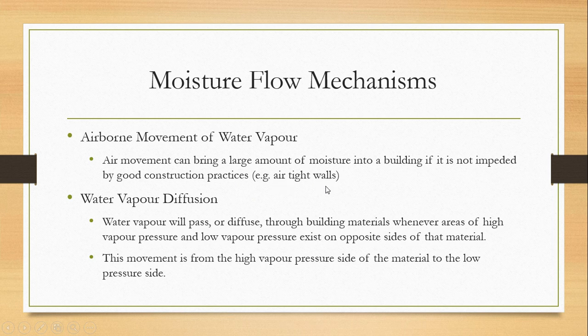There must be proper sealing between your walls, and even your walls and your roof and ceiling. You want to seal off those areas. You don't want gaps in the different panels of your building. Alright, so air can move through there and allow moisture in.